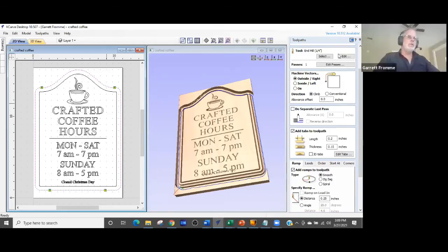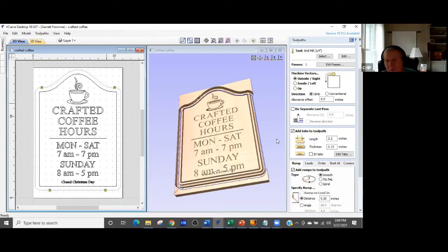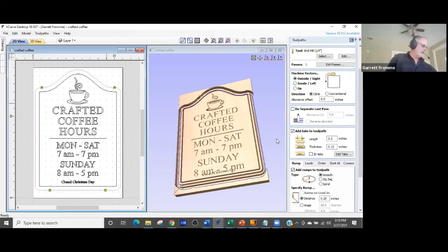Yeah, go ahead and try that before you buy other bits. Are your bits high speed? I'm almost certain they're high speed steel, because they're all one metal, right? The shaft and the body. No, I've got some high-speed steel and some carbide, and quite a variety of straight bits. Yeah, well, work with those. So the one thing that I do see with straight bits, if it's not sharp, you're going to get a lot of bounciness on there.